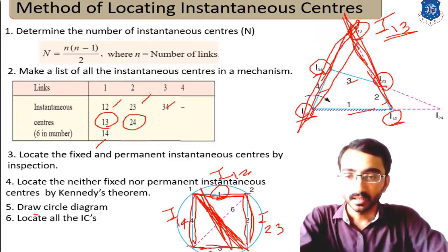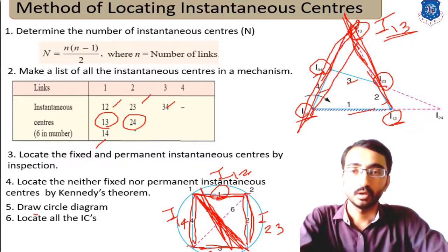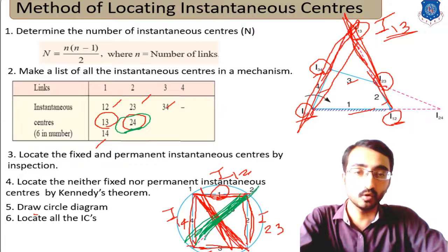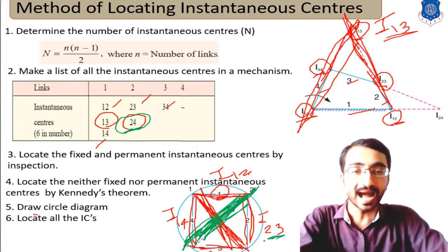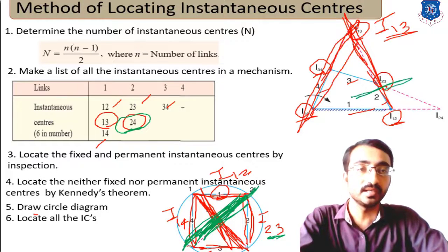Similarly, we can proceed for the second one, that is the remaining 2, 4. Now for this 2, 4 line, let's connect it. To make this 2, 4 connection, we have to connect two instantaneous centers, I23 and I34, in one line. So let's consider I23 and I34. Over here is I23 and I34 is this. So you have to extend this line through I23 and I34.